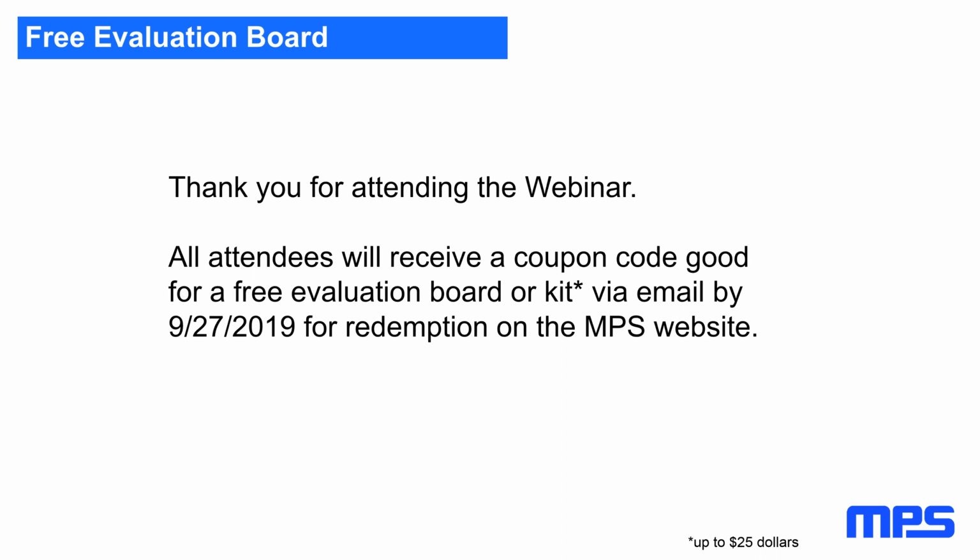The best spot to measure temperature, there are actually three ways. One would be with an infrared thermometer to get the top temperature of the die. If you're interested in the die temperature, you could also put a thermocouple directly on the ground plane, or on the ground areas. You can actually solder it. And if you want to really get the die temperature, on some of our parts there's also the possibility to use an internal diode and calibrate it to get really accurate die temperatures. But if you want more information on it, just ask a local FAE who will tell you the way to do that.